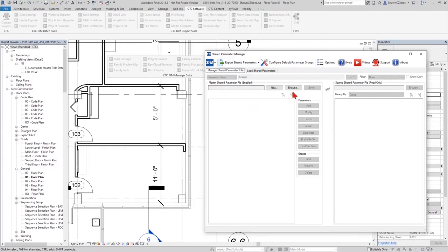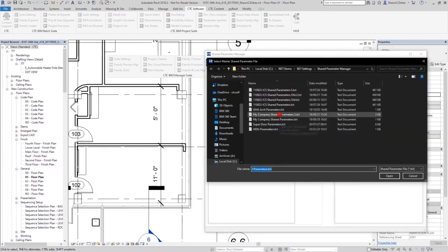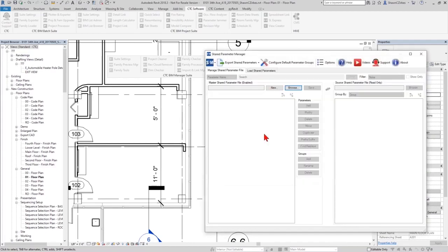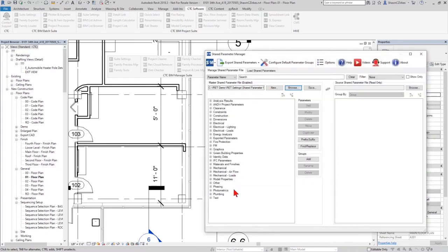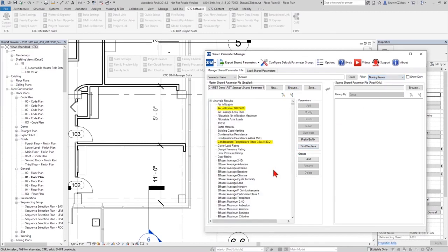With this, what I can do is go find my master shared parameter file here. I'm going to go find, I think it's this guy. I hope it's this one. I have a bunch of shared parameters. You can see kind of the problem of having more than one shared parameter file, right? It gets confusing as to which one's which and which one you're supposed to be using. I'm going to use this one real quick because I can do some quick filtration here on my main shared parameter file, looking for things like naming issues, where there might be mathematical characters in names.